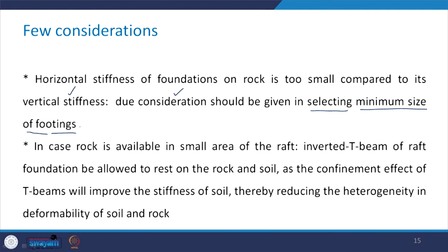So, when you select the size of the footing, you should keep in mind this fact that the horizontal stiffness of foundations on rocks is quite small as compared to its vertical stiffness.